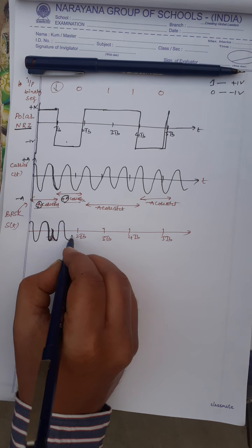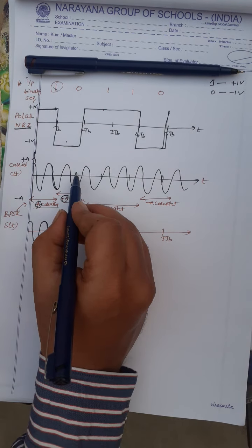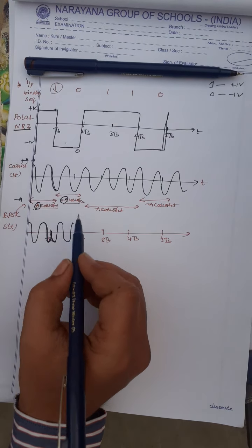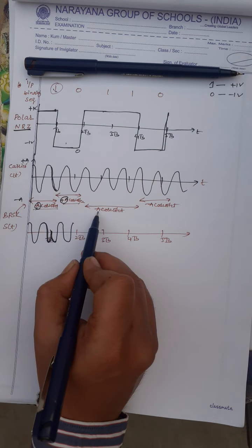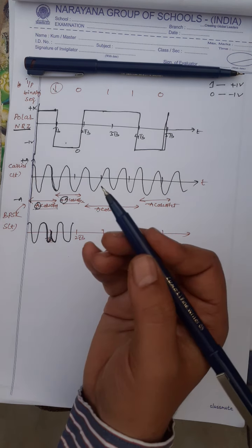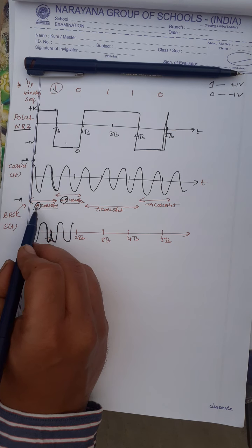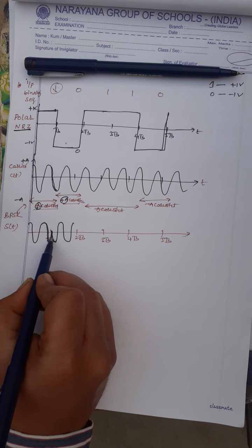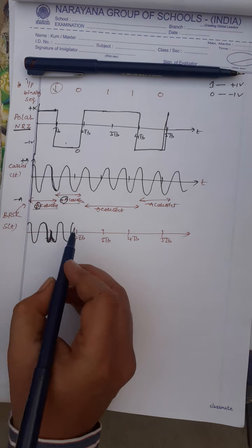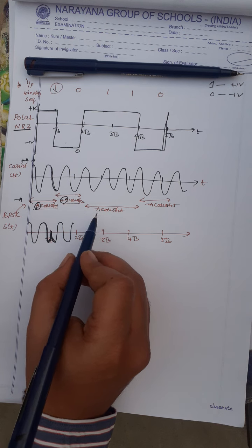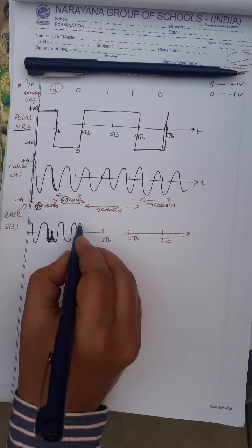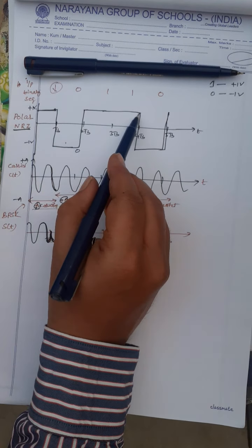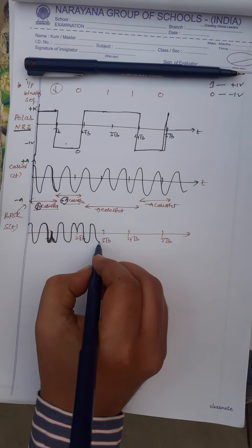Again. Now again at this point from TB to 2TB, the transition is 0 to 1. So because of 0 to 1, this is minus A and plus A. Again 180 degrees phase shift, on the positive side. So here A to minus A is a negative phase shift, right? So you will get a negative transition, that is a negative time reversal. And minus A to plus A, positive time reversal, that is 180 degrees phase shift. Again, if you see here, from here to here there is no phase shift, so the signal will be continuously varied.